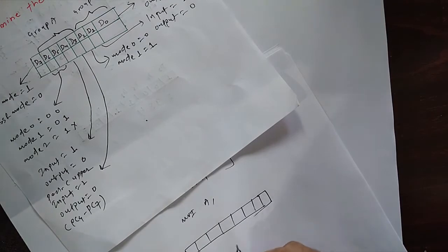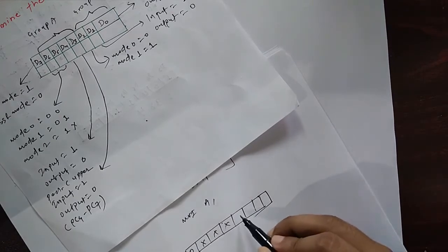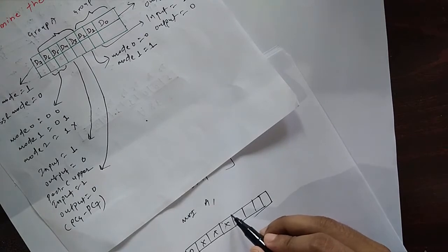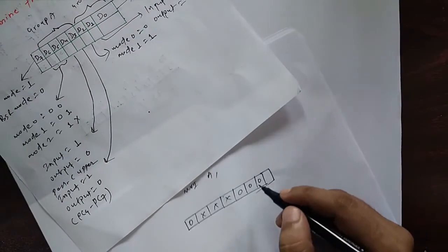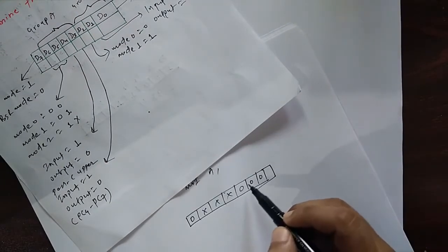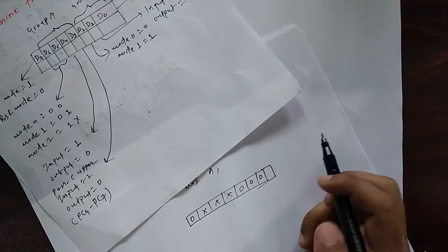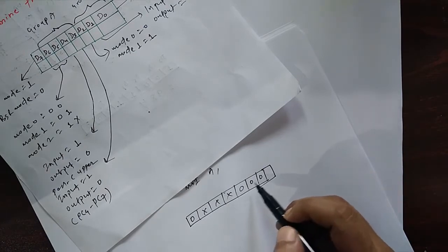Okay, now when setting any of the bits of port C, that will be BSR mode, so we write 0 here, and in setting or resetting the bits of port C, these 3 bits will be don't care. And here if you are setting PC naught, then we write 0 0 0, and if you are setting PC1, then this will be 0 0 1, and if you are setting PC2, then this will be 0 1 0.